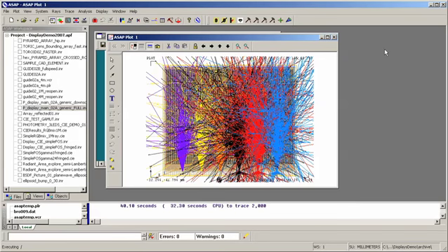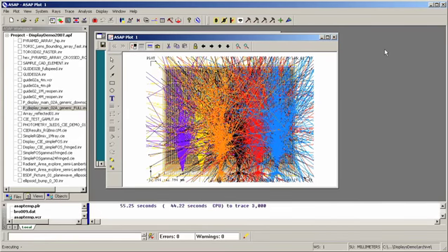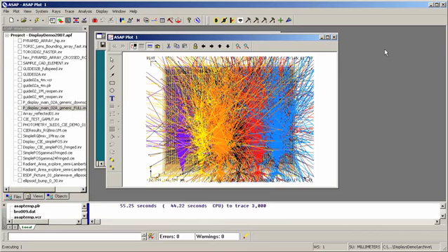It's a reflector, but it's not a perfect reflector. It's a scattering reflector. So now we're seeing scattering results off the bottom surface, which further causes the rays to be propagated across the light guide, and it also causes some of the rays to be directed back towards the origin, which further helps to fill in the gaps between the LEDs near the launch point.